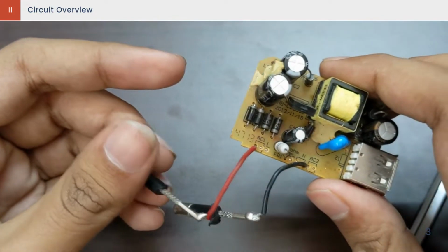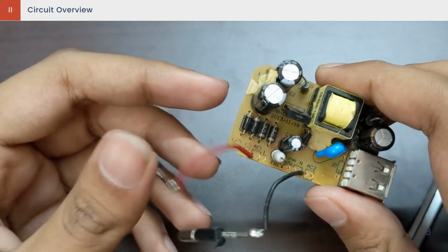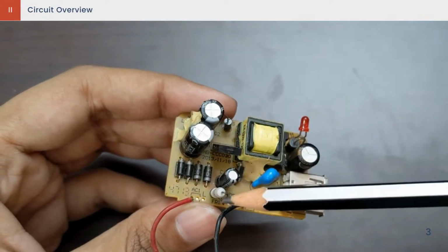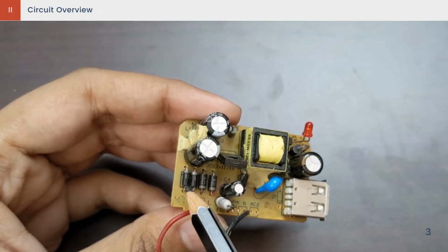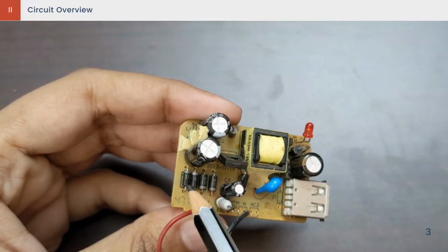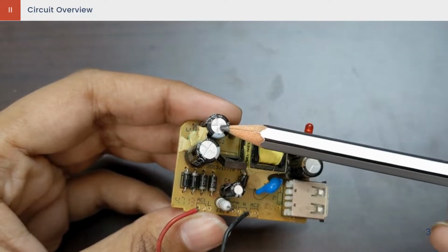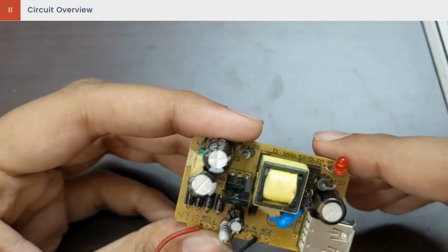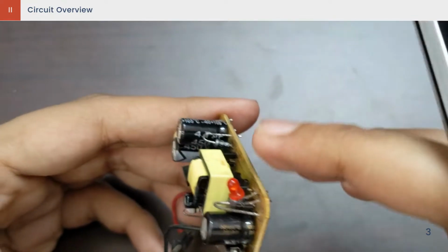First, let's start with this. This is the input section of the circuit, from where we get the input from the direct socket. First, we have here a resistor, as you can all see. Then we have these four cylindrical things, which are the four diodes that act as a rectifier. They are in a diamond shape in the circuit. These two big cylindrical things are the capacitors. If you look closely, you can see these are 4.7 µF each.